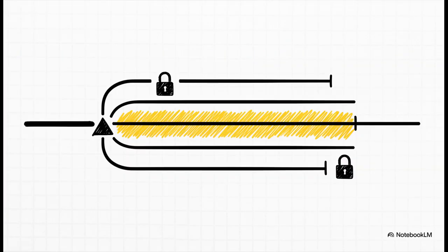The absolute genius of this split architecture is the dynamic routing. At any given moment, only one data register is connected between TDI and TDO. Think about the crazy internal architecture of a modern IC. There might be dozens of different test registers in there, but the shift DR state acts like a master railway switch. Because of the opcode you just set in the instruction path, the data path dynamically routes your serial TDI to TDO connection through entirely different internal chip registers. All the other registers, they just sit completely idle. They retain their state, fully protected from all the shifting data.